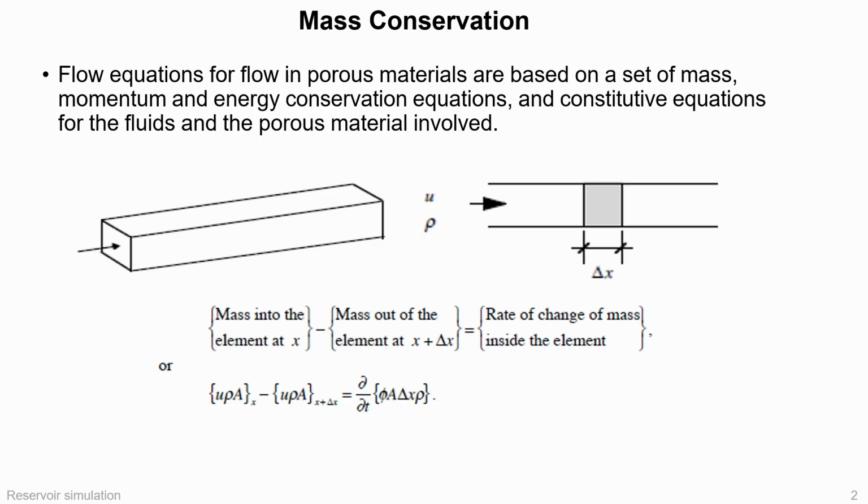If more fluid enters a grid block than leaves it, mass accumulates and pressure or saturation changes. If more fluid leaves than enters, the block depletes. This is why mass conservation is one of the most important equations in simulation. Without it, we could not realistically track reservoir behavior.